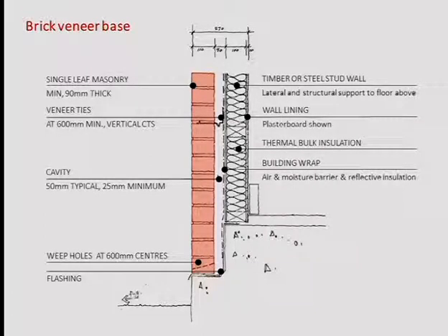Where are the structural elements? Well, the structural elements are hidden a little bit behind this insulation. We see the bottom plate of the stud frame here. We see a kind of noggin here, but the stud, the vertical one, is hidden behind that insulation. That's structural element number one. Without that, we are not able to sustain the wall and the upper floor.